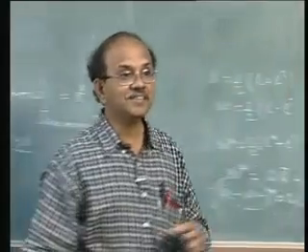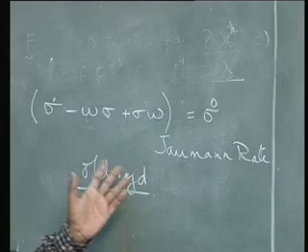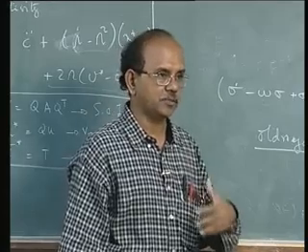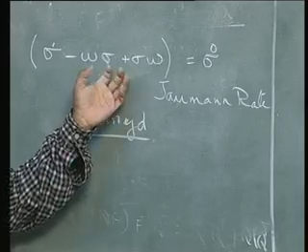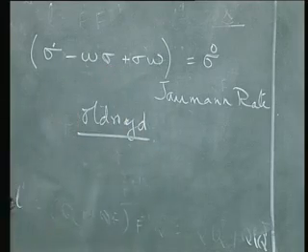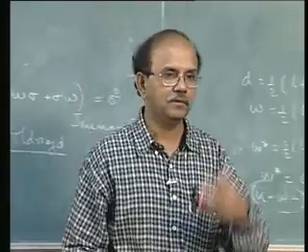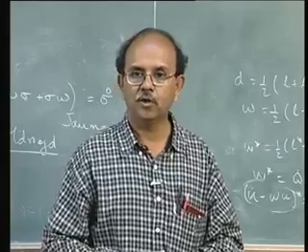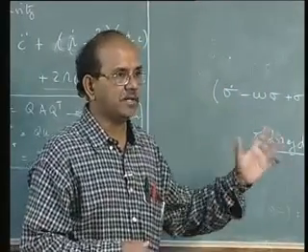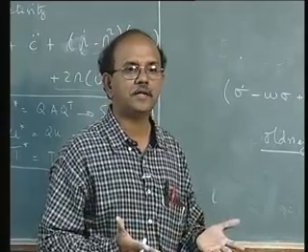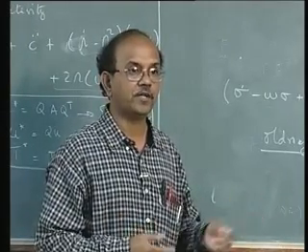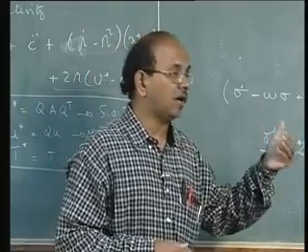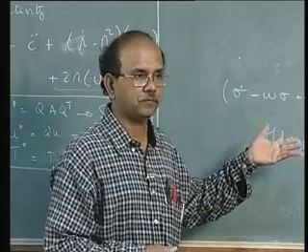These rates take into account such motions due to q dot. Physically, you are also moving with those q dot fields and then looking at the derivative. Why was sigma dot not an objective quantity? Because there was a q dot there. That q dot is removed in this fashion.